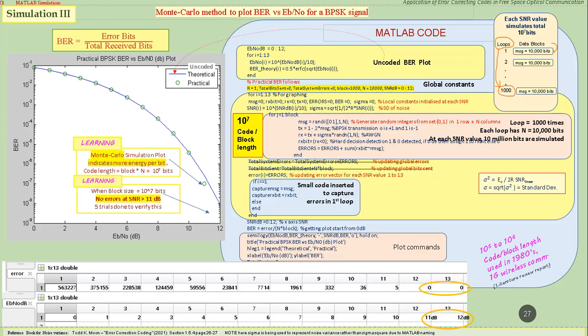And further, I have written this received message. Now the received message must have traveled in air, and I have added the noise to it. I have added the noise power. Noise power is variance. So sigma, the standard deviation, is multiplied by a random number generated from a Gaussian distribution. We calculate our sigma based on the formula that we showed before, and as per the SNR, the sigma value will change.